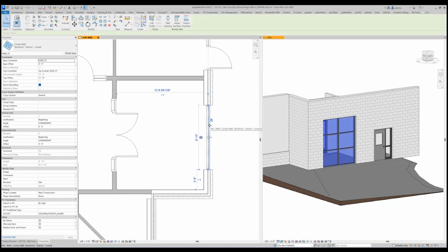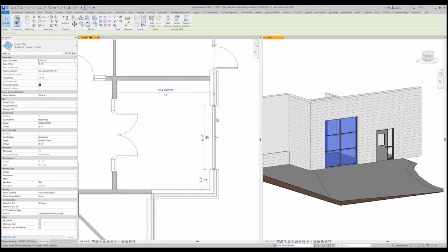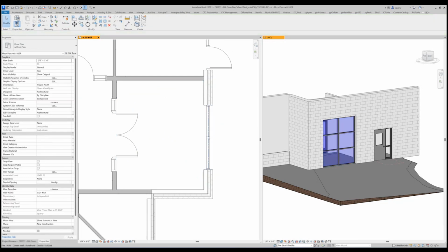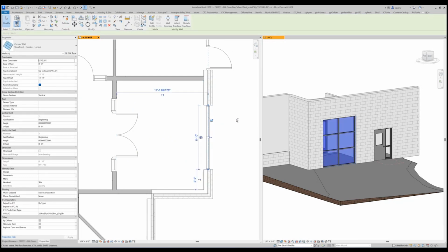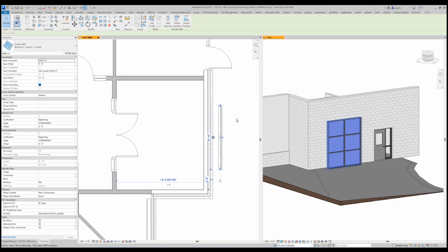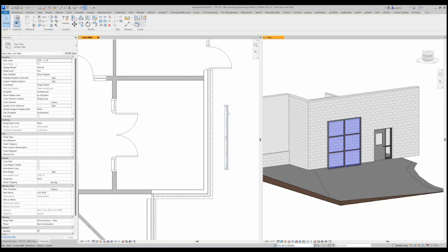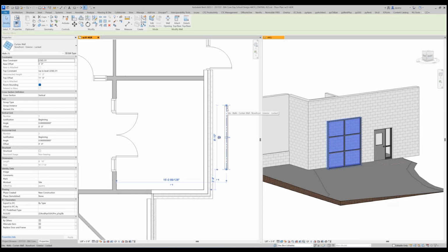The one thing that I forgot to tell you is, I'm going to move this out of this wall, hopefully. I want to unlock it. After I draw that in, the first thing I do every single time when I do a curtain wall or storefront is I right click these ends and disallow join. And there's a huge reason for that.